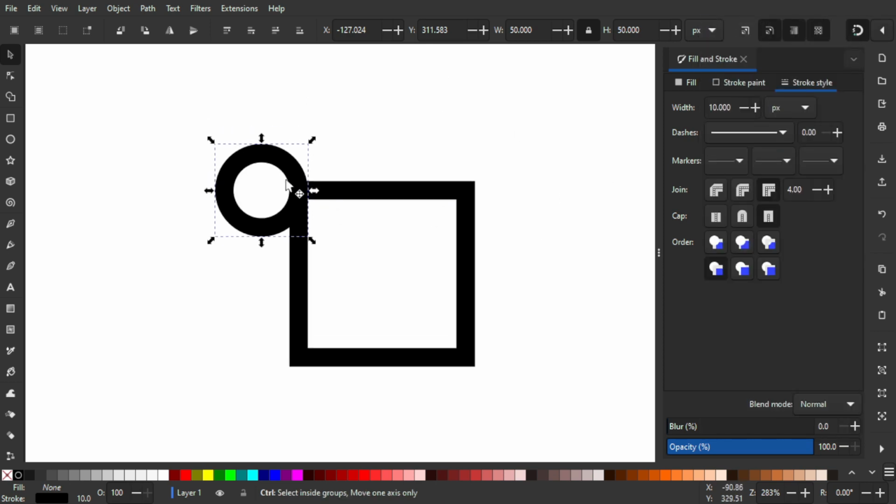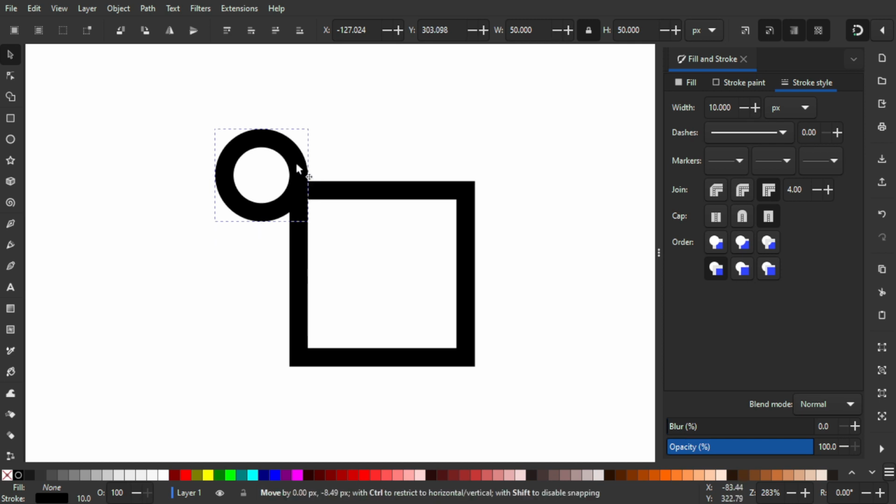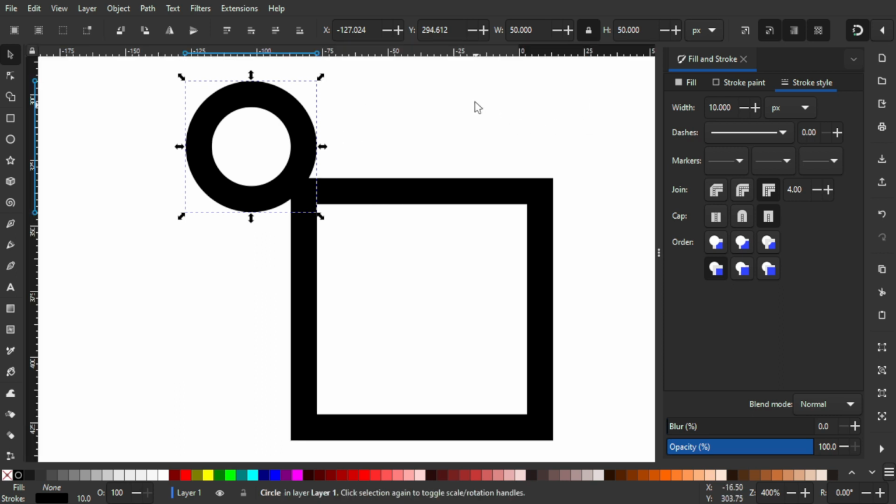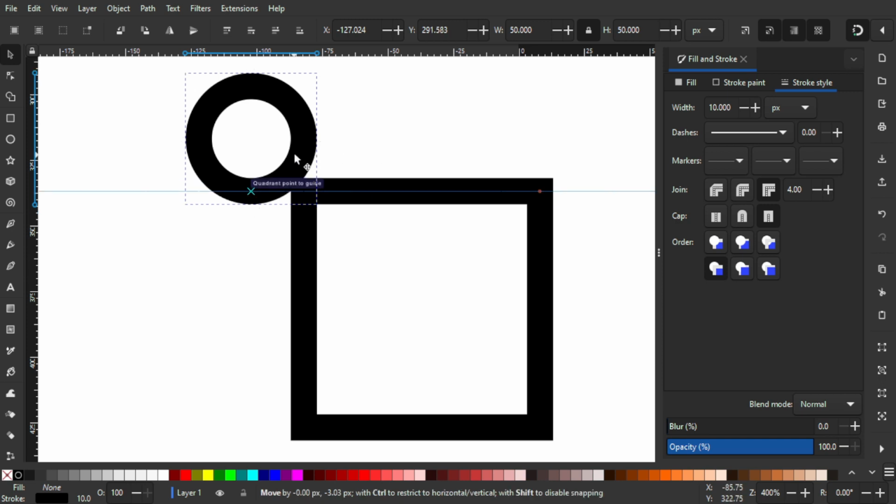Alright, now because we already snapped it over here, so hold Control and drag it upward like this. Want to have this bottom part parallel to this line over here, but it's kind of hard to eyeball it, and we need to be precise. So press Ctrl plus R to bring out the ruler over here, and I'm gonna hold left click and drag in the horizontal line over here, and I'm gonna hold Control and move it upward like this.